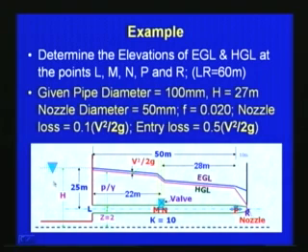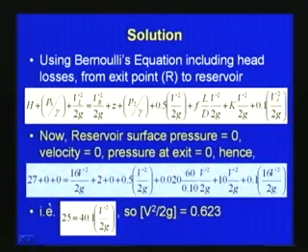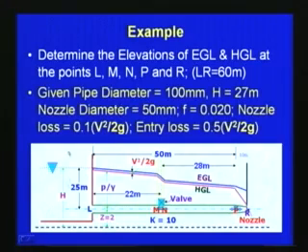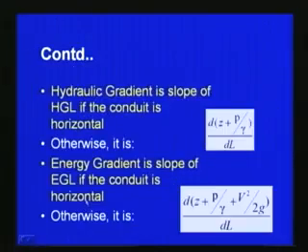You can see that with respect to this reservoir or tank, here the total head is H, plus we will have the pressure P1 by gamma. Actually it is atmospheric, so it will be 0. Then just before the entrance of the pipe, this gives the velocity head, but here we will be assuming the velocity as 0.